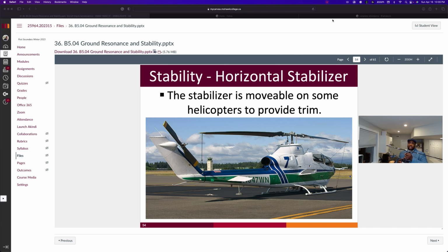We know that as the helicopter wants to move forward, the rotor will have a tendency to tilt forward, tilting the helicopter with it. To provide a more stable conventional ride for passengers, we need to lower this very high tail. So horizontal stabilizers are inverted so that they produce lift in this plane to lower the tail of the helicopter in forward flight. I repeat, horizontal stabilizers use an inverted airfoil that helps to lower the tail of the helicopter in forward flight.